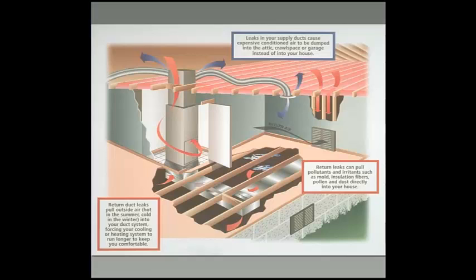If you're running your mechanical system either through a crawl space or up in your attic, this is not just an energy penalty. If I'm pumping conditioned air out the top of my building and I have disconnects, that's a big energy penalty. Up in our neck of the woods, we tend to keep our ducts warm, but there's still builders running through the attic.